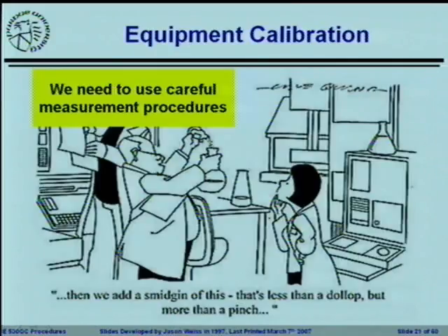I will point out that one of the first opportunities I had when I came here 8 or 9 years ago was to put a calibrated cylinder into one of our testing machines and realized that we were actually measuring about 40% of what should have been measured coming out of the machine. That is a big issue. All right? You're getting strengths that are 40% of what you think they should be. You need to check this carefully on a routine basis.